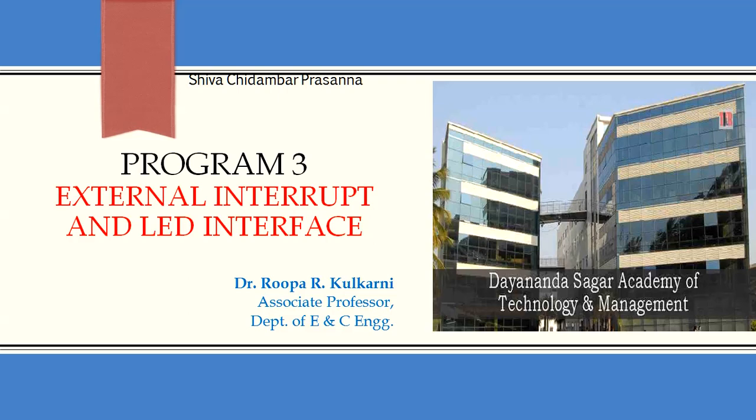Now, don't you think this is really advantageous? On the contrary, if the processor has to keep on monitoring the temperature of the furnace, the processor time is unnecessarily wasted. But with an interrupt, you have the advantage of saving processor time, and the service is provided only when the external source, or your on-chip peripherals, require the service of the processor.